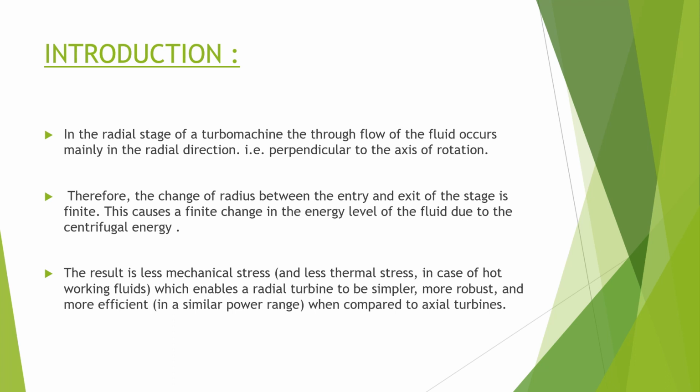First of all, introduction. In the radial stage of a turbo machine, the through flow of the fluid occurs mainly in radial direction, that is perpendicular to the axis of rotation. Therefore, the change of radius between the entry and exit of the stage is finite. This causes a finite change in the energy level of a fluid due to the centrifugal energy.